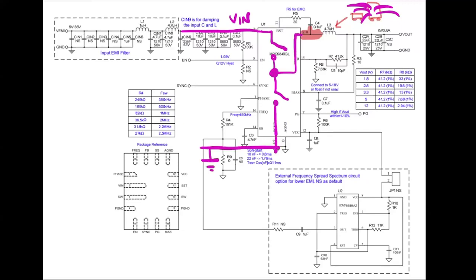So you can see here, these capacitors that are represented with this. What happens with these capacitors? These capacitors have the function to give to the device all the transients we need to work as expected. And this loop is really critical. This loop must be very, very, very small. And this is what you can find in this design.